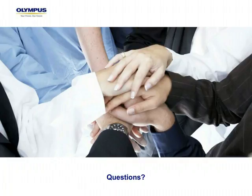So we had one, can it be used on stainless steel? Yes, it's a good question. I mean, stainless steel varies a lot by the grades and whether it's austenitic or not, and then actually the process it goes through can change that as well. The answer is yes, and we do a lot of acoustics on that. Usually we design and baseline them for carbon steel so that we can use something homogeneous to be able to give out numbers like 2 to 80 millimeters in carbon steel, dead zone of X. But stainless steel and all the other variable materials are possible. It's just more of a, we'd like to do some acoustic tests to make sure.